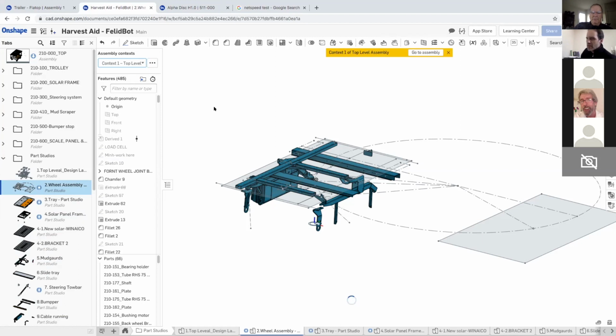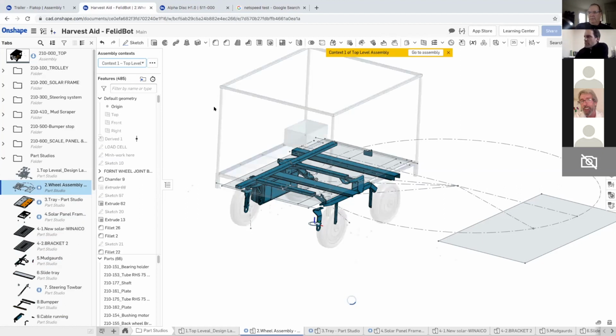So, I'm trying to put this together myself. But they use the word context, and Bruce mentioned it, because I just have to reference how I've seen other systems do it. Unlike SolidWorks, when you do an external reference, when the assembly updates, everything just updates. So if you build one part off of the other and you use an edge, if you move that part with a mate, the part that's built off those edges also updates, and then you have this cascading effect where all your parts can fall apart, because they were assuming that they were built in a certain orientation.